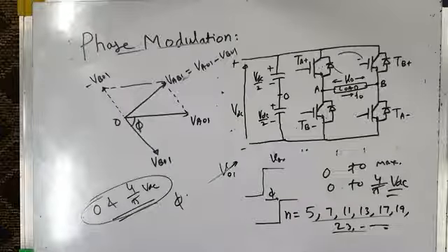And among the low switching frequency PWM, we go for selective harmonic elimination technique, or offline optimized PWM technique, or what we call stored waveform PWM technique, where once the objective is known to us. The objective may be reduction or minimization of weighted THD of voltage, or it may be minimization of pulsating torque, or minimization of motor losses, or minimization of total losses, that is the minimization of inverter losses and motor losses.